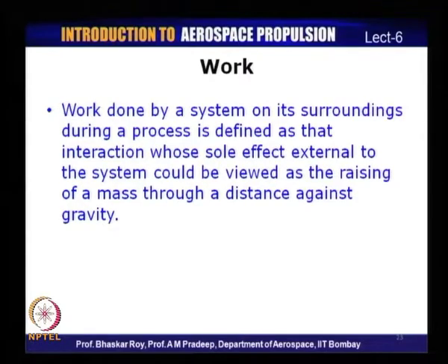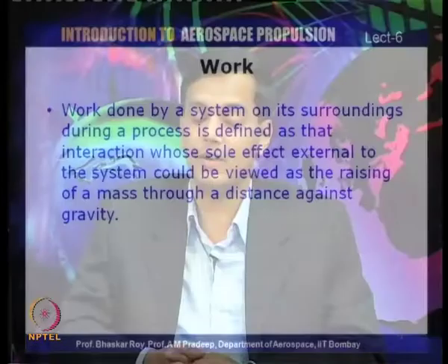Now, let us define what is meant by work. Thermodynamically, work done by a system on its surroundings is referred to as a work interaction if the sole effect of this interaction can be viewed as raising of a mass through a distance against gravity. That is, work is said to be done by a system on its surroundings or vice versa if the net effect can be considered to be raising of a particular mass through a certain distance against gravity. So, this is the thermodynamic definition of work.